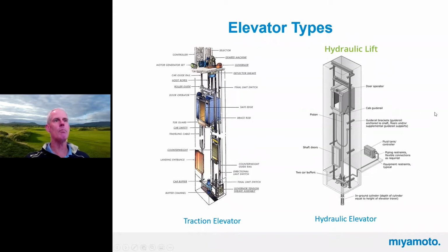So really, our piece of this is, we design the pit, we show the pit, we do all the reinforcing for the pit and all that sort of stuff. We coordinate with the architect for the size. And then, I don't know if you can see my cursor or not, but the elevator guide rails themselves, which are these things that the elevator runs up and down on vertically, will be laterally supported by our guide rail supports. And we're really the person responsible for the guide rail supports and attachment to the structure.